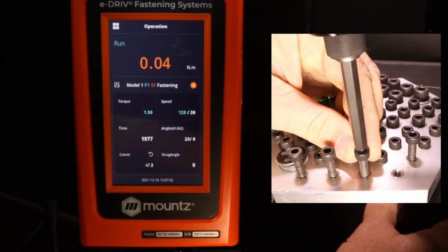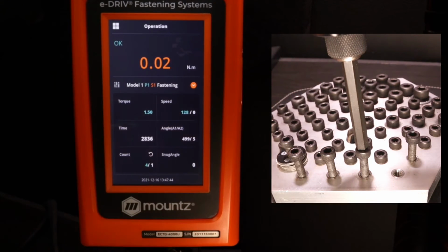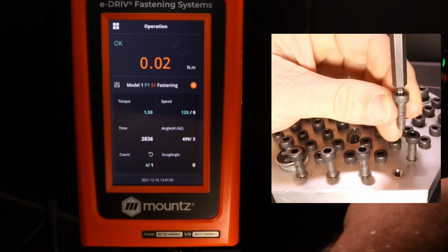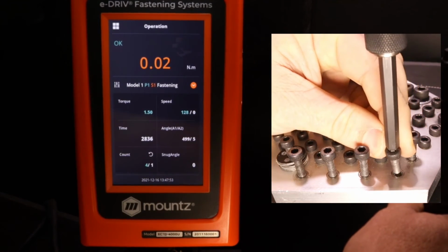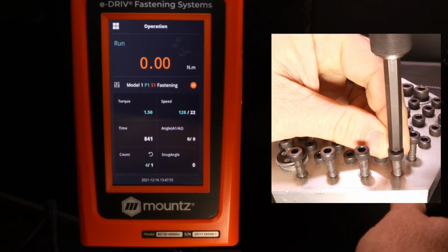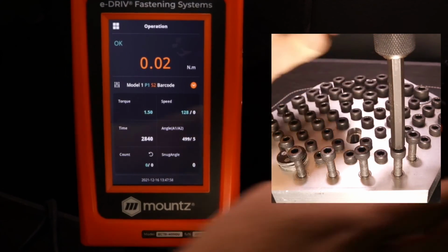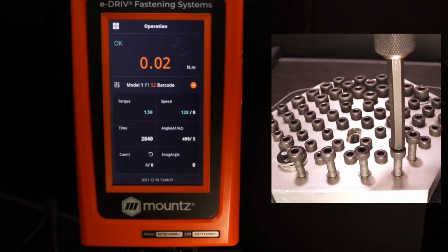and this could also be done, as I mentioned, in one actual rundown, but we just wanted to demonstrate how this might work in this type of scenario. Maybe you have a gasket type of rundown that may need to be seated in a particular order, and if there is any type of cross-threading that may happen, that could be an issue. So if you want to set and make sure that all the fasteners are ready to go, and then go ahead and do the tightening, this would be a scenario that you could use.